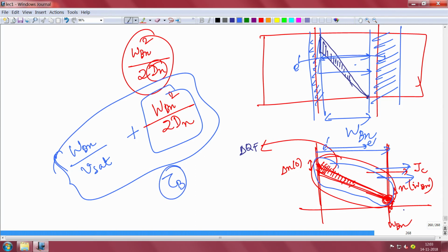So basically a small change in the signal will give you a small perturbation in the charge that you are storing in the base, and there will be a small spread here also, because it's a finite velocity, not an infinite velocity. So the collector side carrier density also rises, there is a small spread here, and you need to supply an additional charge that will make sure that there is a spread here and there is a spread here.